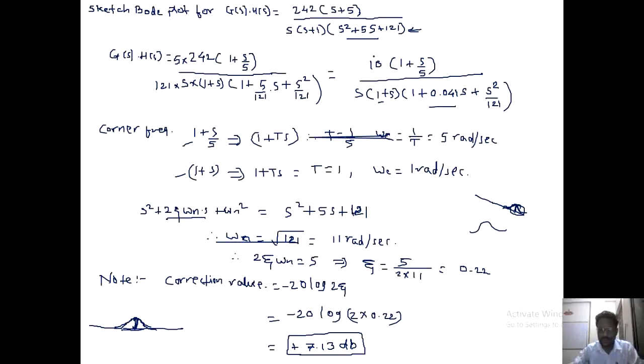So the parameter, then magnitude, or individual magnitude, then cumulative magnitude, then range and slope. So the very first parameter is k. K is the resultant gain of the system, that constant value comes out. So in the standard part, the constant is 10, then pole at origin, then simple pole, then simple zero, and then quadratic pole.